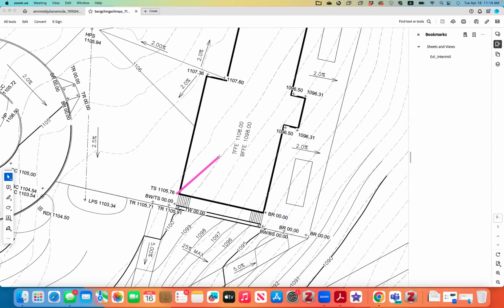The top of stairs will be determined by this distance, by your plaza. And this is also determined by your plaza because this whole surface is graded the same. So the top of the ramp is the same thing. They need to be determined by the contours, as well as the top ramp over there. Yes, both of these are the same. This should be a single line. There's no curve there anymore.